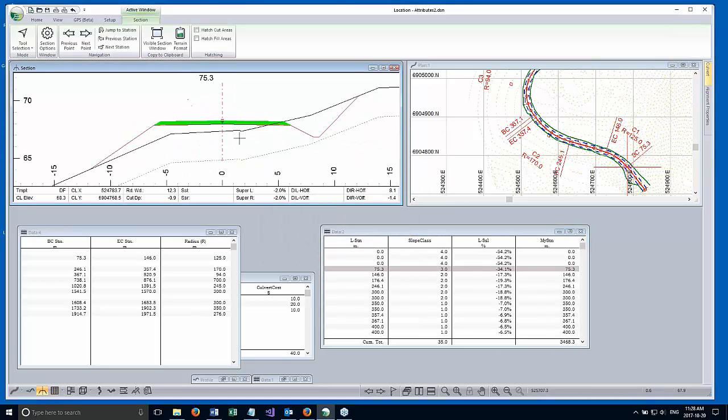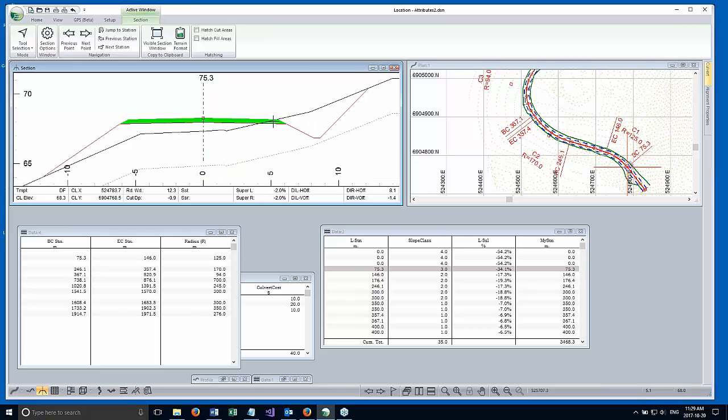On the cross-section there are identifiable points, and if you just hover over a point on the cross-section, you'll see at the bottom of the hover tip it says DIR. That's a point code on the template, ditch inside right. For this particular template, other templates might not have it. There's ditch outside right. There's RER, and you notice some of them have multiple point codes. That's okay. So depending on your template, you can get these different point codes.